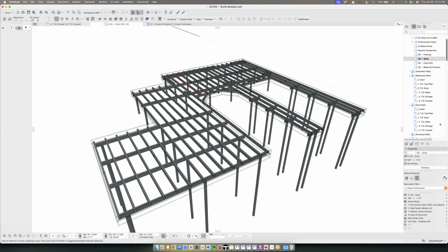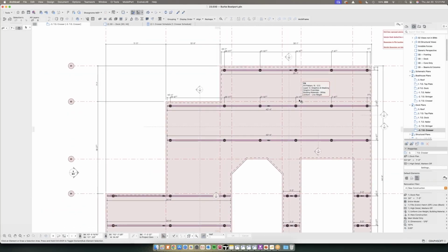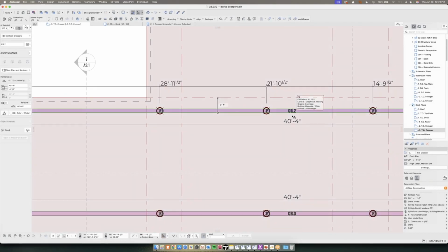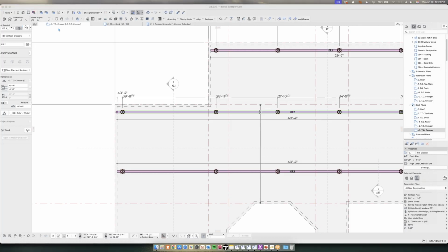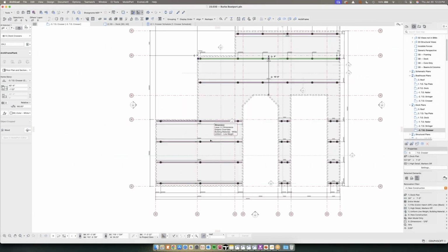In terms of translating this into 2D documentation, we can look at this here. I have a dock plan phase. One of the beautiful things I like about ArchiFrame is we can see that I have this steel element here and it's tagged. ArchiFrame automatically tags the elements from the element ID box that you can see here. So if I were to change that element tag, that element tag automatically updates. But the beautiful part that I like is that everything is centered. So you can tell through the display menus within ArchiFrame, which is just a built-in plugin here.